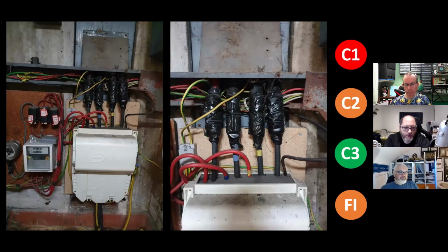This larger earth cable, I want to see underneath that header to actually see if it's sweated on or if it's just disappearing. I think I would more than likely assume that goes into a duct with that supply cable. So that cable there looks likely to be connected to that cable. So that could be a bonding conductor for all we know. That could be a gas or water bonding.